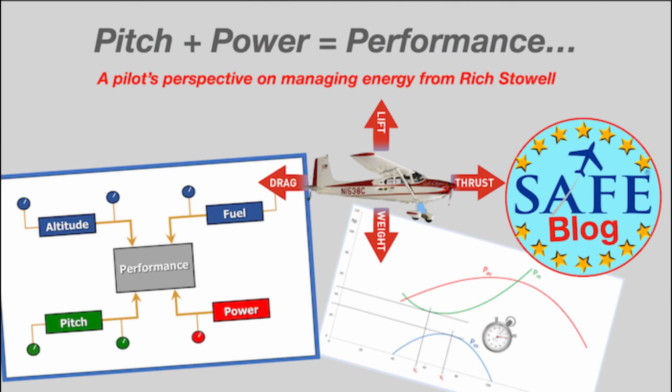Power management. Unless the aircraft has an autothrottle system, you must adjust the power to an appropriate setting when performing any climb, descent, or level off. You cannot allow the aircraft to exceed any applicable speed limitations during a descent. During a climb at a vertical speed that the aircraft cannot sustain, the FD/autopilot may command a pitch that results in a stall.